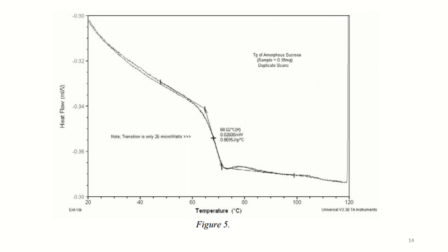The value of the second heat is to not only check the reproducibility but also to verify that the sample is dry. A wet sample, even with a few percent moisture, would have a lower glass transition temperature the first time that it is heated in a crimped pan.